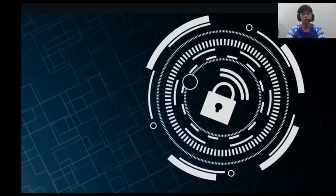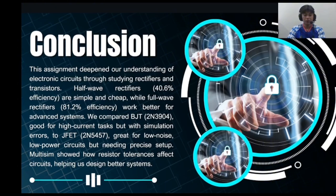So, to conclude, this assignment helps us understand electronic circuits better by comparing different types of rectifiers and transistors. We saw that half-wave rectifiers are simple but less efficient, while full-wave rectifiers offer better performance for advanced systems. On the transistor side, BJT is suitable for high current applications despite some simulation error, while JFET excels in low noise environments with precise setup. Simulation using Multisim emphasizes the impact of real-world factors like resistor tolerance, showing us how to build more reliable systems.